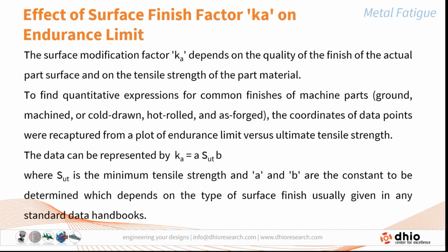Now, to quantify the expression for a common finish, whether a ground machine part, or a cold drawn, or a hot rolled, or a forged part, the coordinates of the data points were recaptured from a plot of endurance limit versus the ultimate tensile strength.